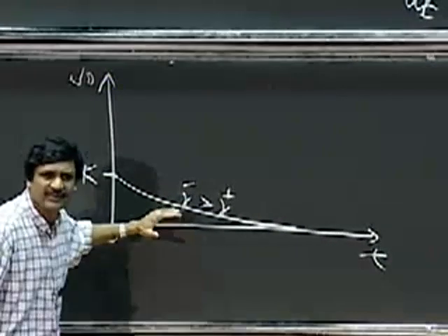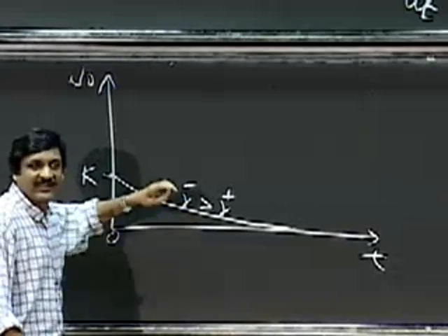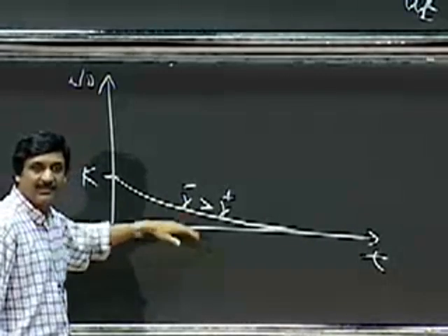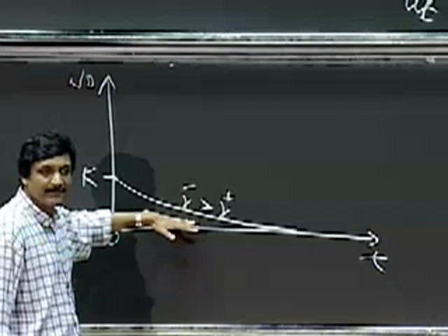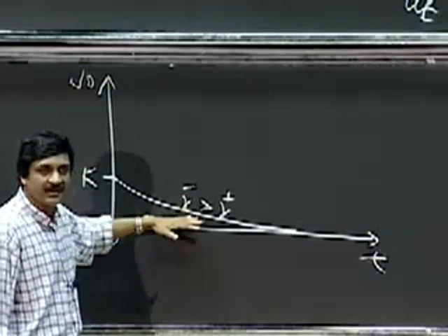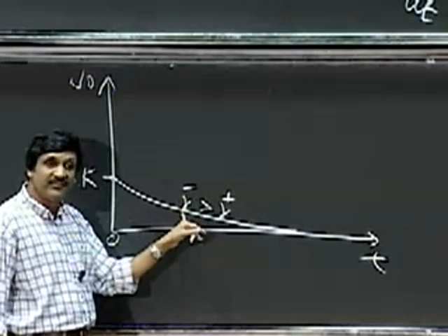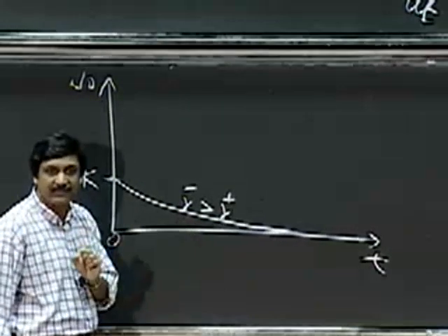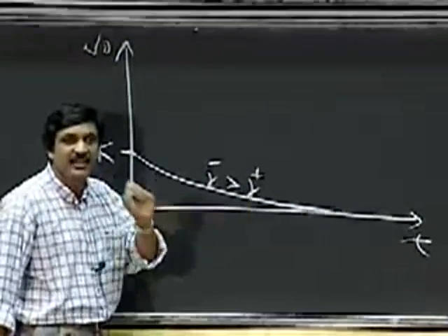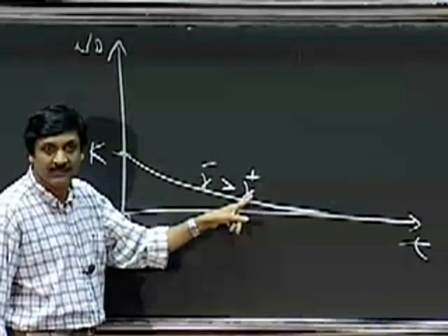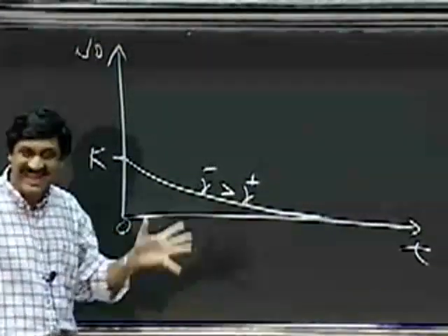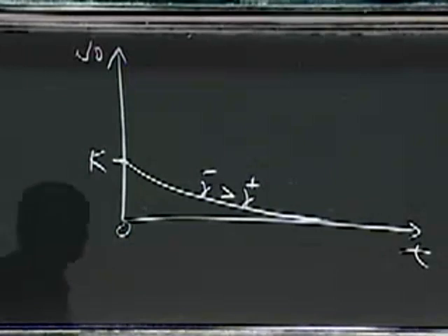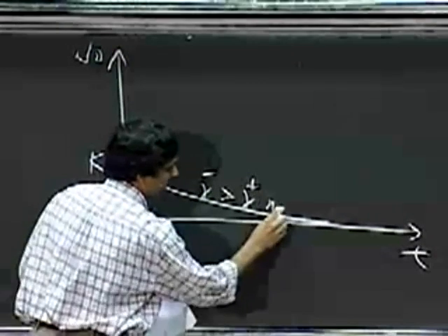So intuitively, what am I saying here? All the gammas and other pieces aside, what am I really saying in English? If the portion of the output fed to the negative input is greater than that fed to the positive input, then I have net negative feedback.